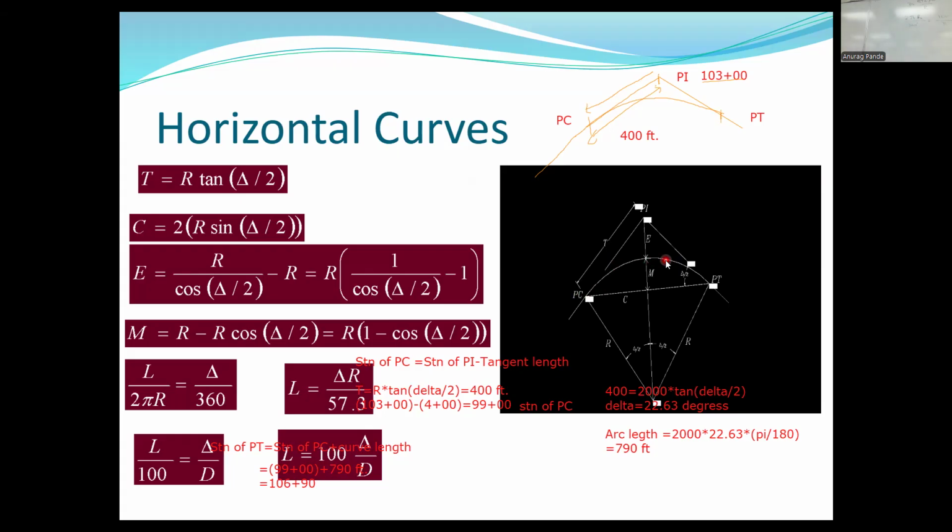Okay. So then what you'll need to do is find what the angle is. What is just this angle subtended up to this point? Then you can find the arc length only up to this point. Okay. So remember that you might have to solve problems like that. Any point on the curve, it could be here, could be here. If you're going full curve, then you're going all the way to PT, but just make sure that you can do that. All right.